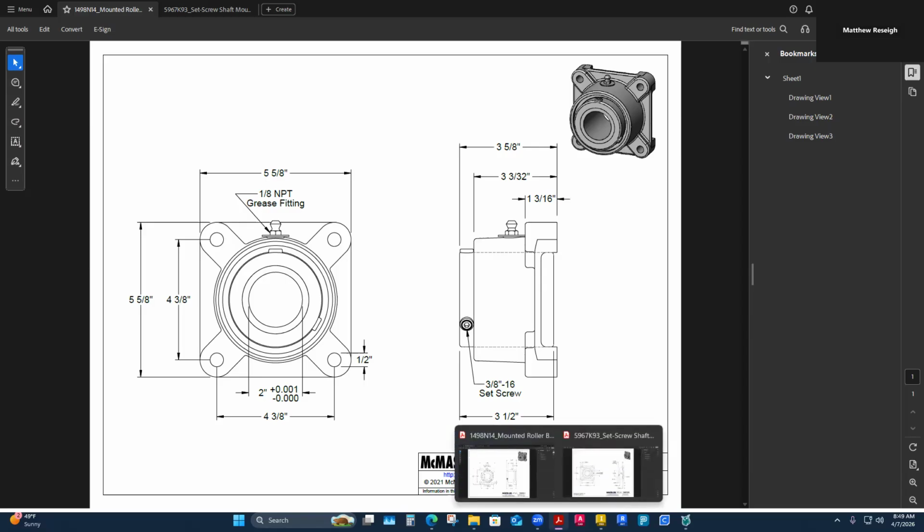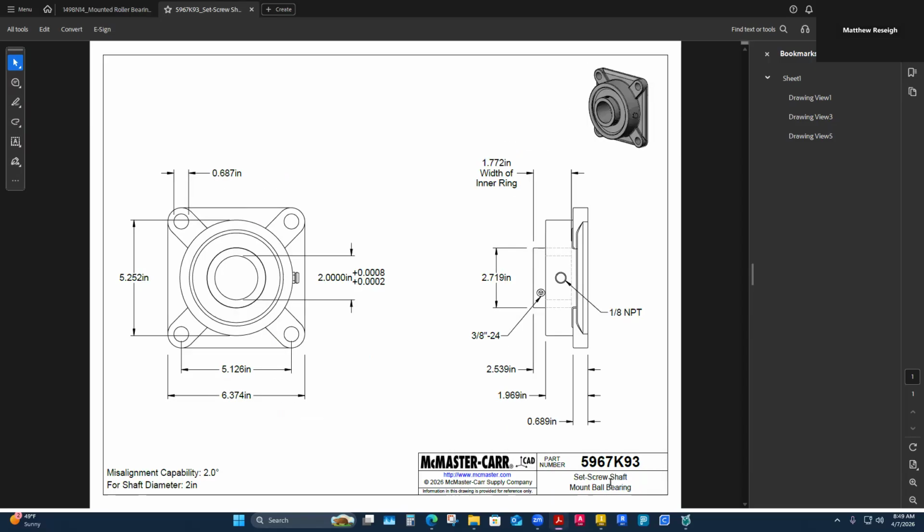On this other one, though, just by the nature of it, for whatever reason, the way it's built, they put a 0.687. That's almost 11/16. 0.6875 would be 11/16. It's a fairly large hole. So I could put a 5/8 fastener on there. That's 0.625, and that's a common fastener. Looks like I chose 1/2 inch. I'm not sure what I was thinking.